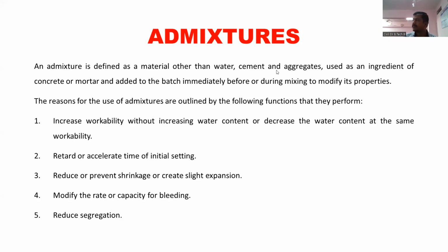And what is laitance? Water comes along with the cement paste. When the water along with the cement comes at the top surface, you call it laitance. Please remember the small difference between bleeding and laitance. In case of bleeding, only water comes at the top, and in case of laitance, water along with some particles of the cement will come at the top.